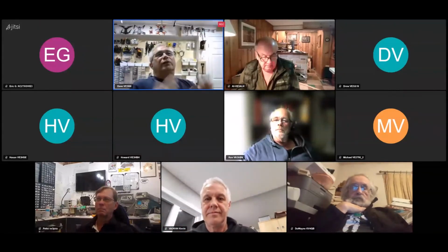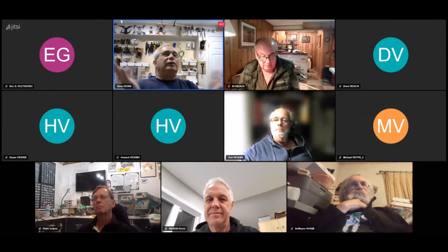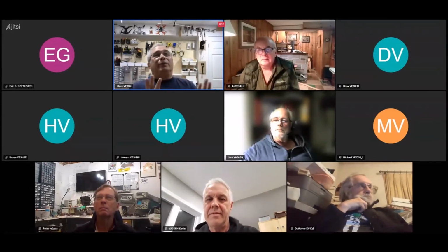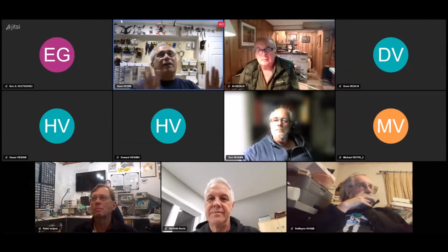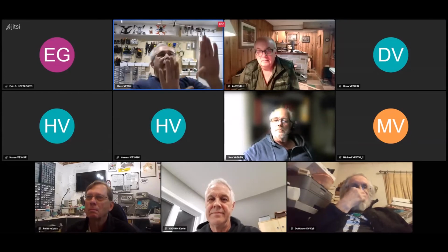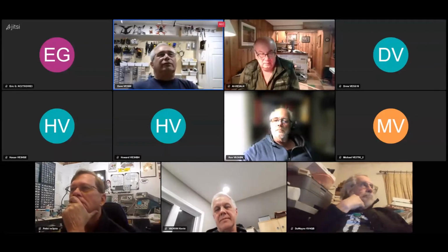Stuff like that I might do, because then you're using controllers that are off the shelf, and you just have to program them. They're all PIDs, by the way. All these controllers, they all have PIDs. So you've got to go in and tune the PID to get it to use dual motors to make it level itself.